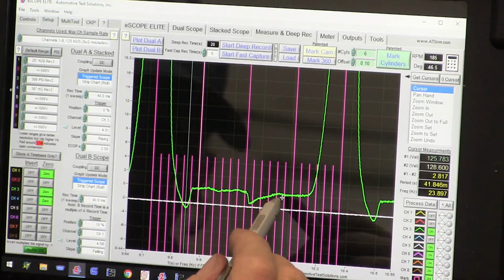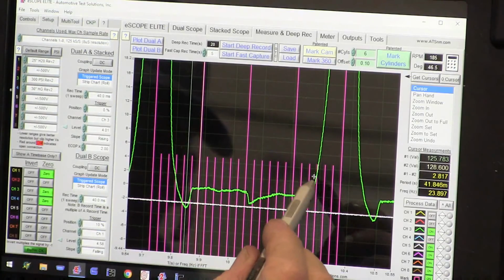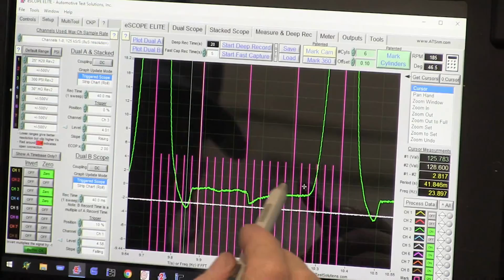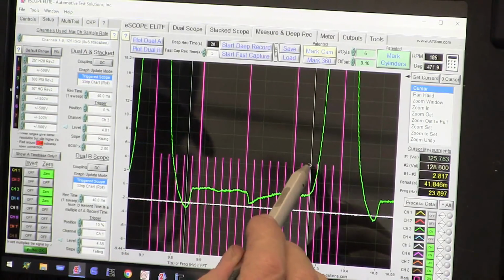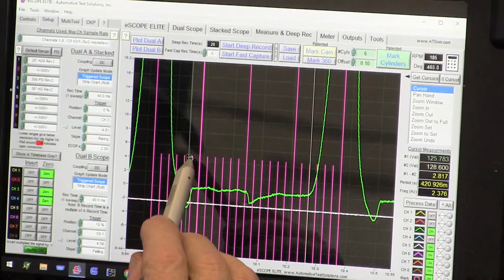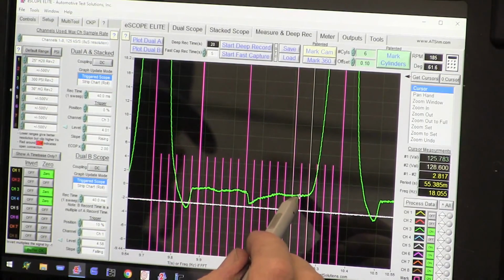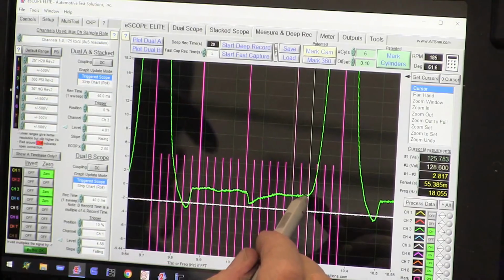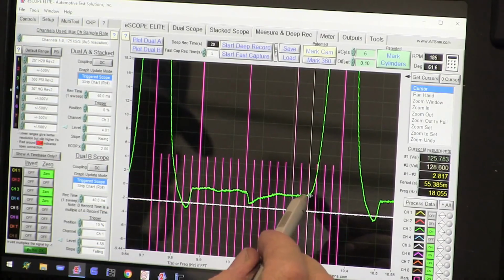Now this looks much better over here. Do you see how I'm going all the way to 60 and then I'm rising on the intake? Like this looks better. I come across, that's 30, 60. We can measure that again. Now rather than being down here at 28 or 30, now I'm rising at 61. And usually, again, these rise at about 70 degrees, 75 degrees. So it's still off, but it's way closer.